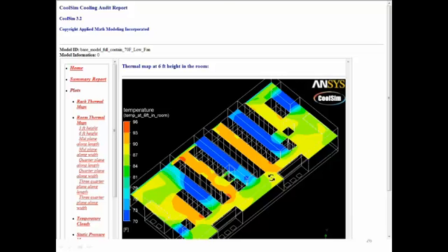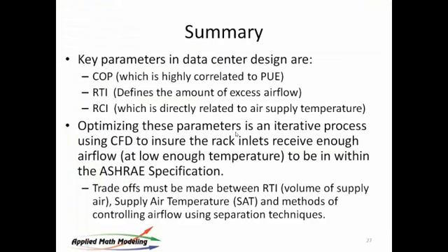Sometimes the human element enters into these things, and people get very nervous about the fact that they're in a data center that's 90 degrees. You need to remember they're standing in the hot aisle, but still it does make people a little bit nervous. I therefore tend to favor the alternative, which is, of course, the hot aisle contained. Okay, so that's it for today.